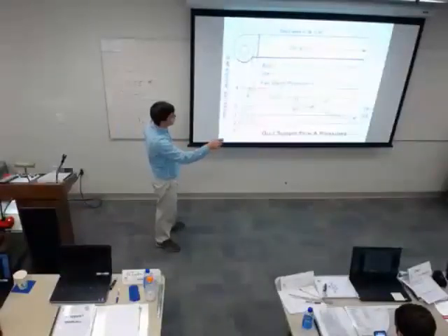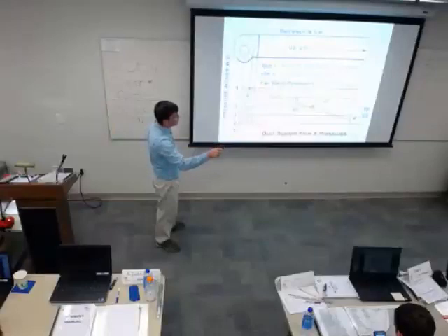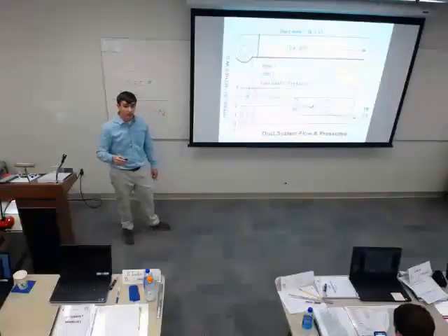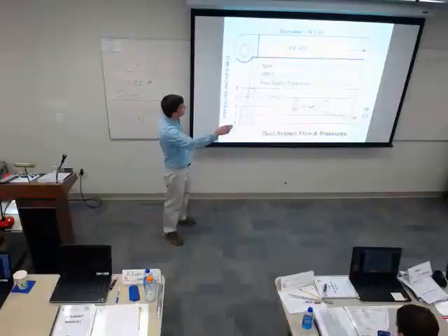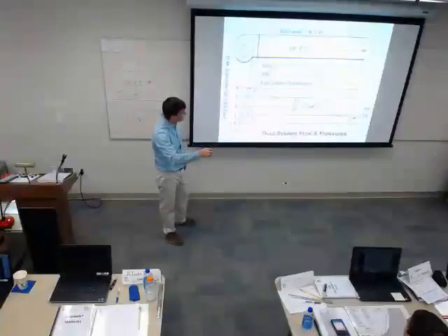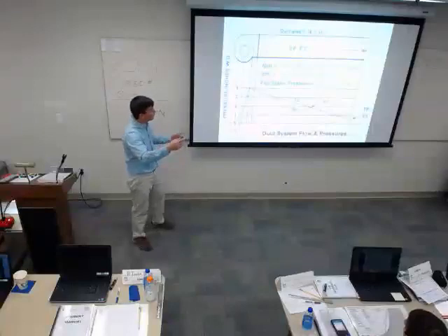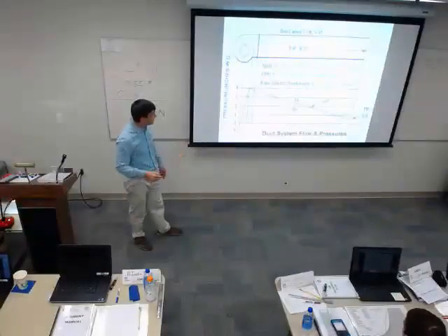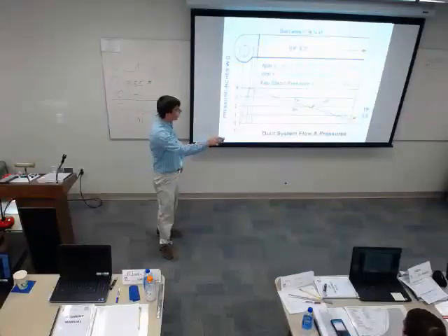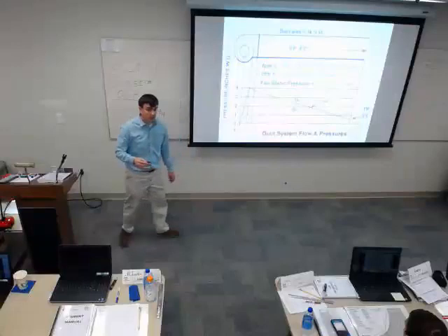So knowing this velocity pressure, I can calculate my feet per minute, my velocity. And then back to the equation you mentioned, I was given the duct area in this problem, which we calculated earlier. Multiply our feet per minute times our duct area to get our airflow rate, 30,000 CFM.